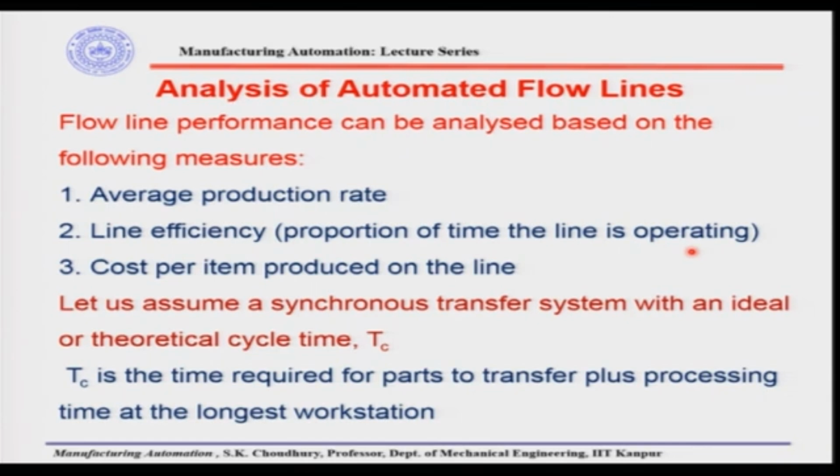Well, to analyze the automated flow lines, let us assume a synchronous transfer system with an ideal or theoretical cycle time Tc. What is synchronous transfer system? I will remind you that it can be the inline or the rotary indexing, where the parts or the sub assemblies are being transferred and then they stay for some times for the processing to be over.